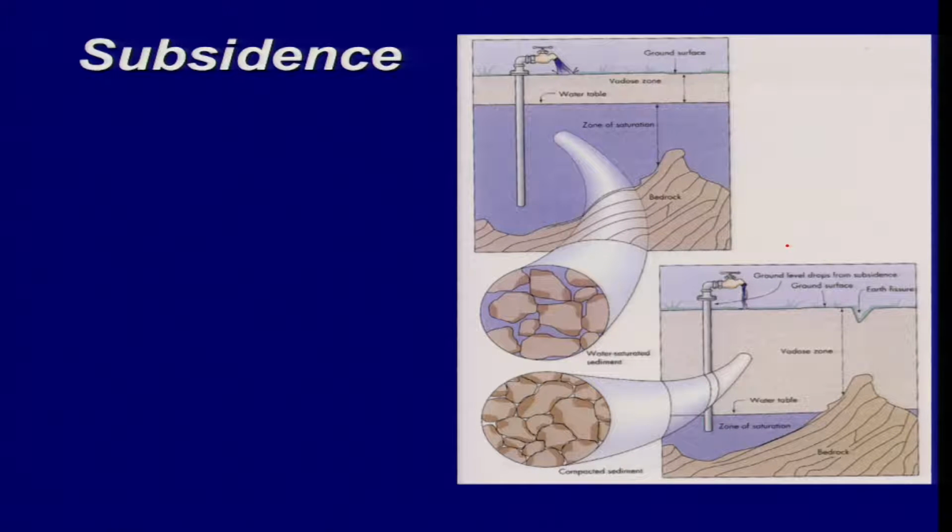So, if you look at the profile of the soil and the groundwater, what you will see is that you have a vadose zone and you have a zone of saturation, where you will have the pores, and pores are occupied with the water. And this is the aquifer from where you will pump up the water. Now, if you keep on pumping the water and the recharge is very low here, eventually this vadose zone will have no water left.